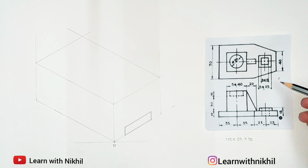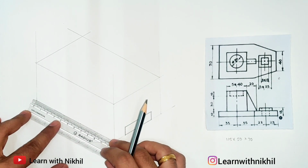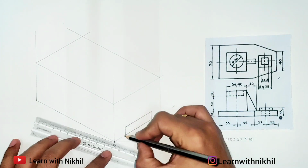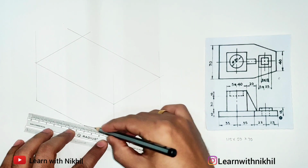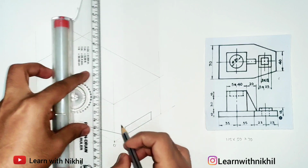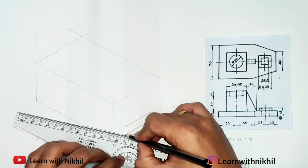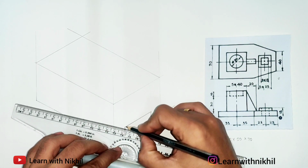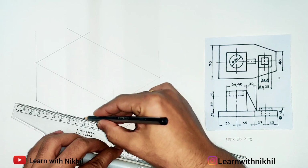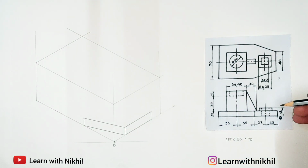Now for drawing the slant line, you don't know the length of the slant line, you know this length. So this total distance given is 35 plus 35, that is 70. It is given in the bottom view. So 70, I have marked a point. Now through this point we will join this. So directly you will get the slant line. Same this line we will construct at a height of 10 millimeter above. So from here light line drawing, this will be 10 millimeter, and using this as the reference line, we will draw the slant line over here also, and you can join this dark. So this part is done.